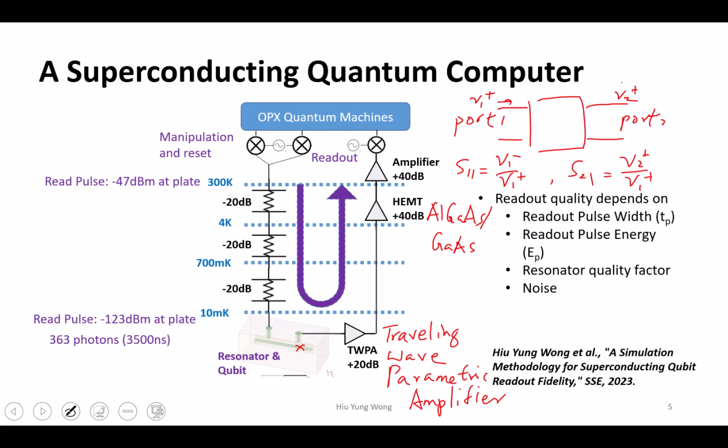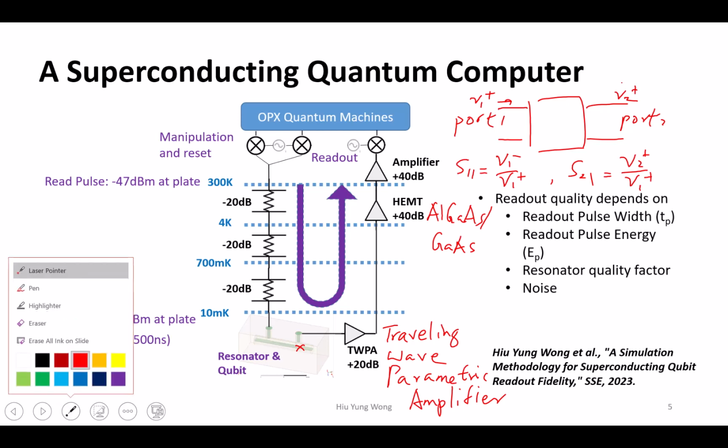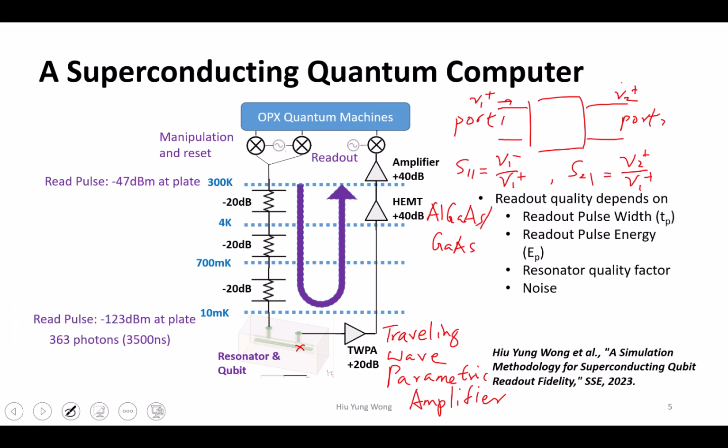Remember when we talked about the quantum dot? This is one of the platforms where you can implement the silicon qubit quantum dot, because they form the two-dimensional electron gas. And here, the so-called high electron mobility transistor forms the two-dimensional electron gas, and they don't have any impurity scattering because the dopant is actually placed away from where the electrons are. It's good to maybe talk a little bit about that.